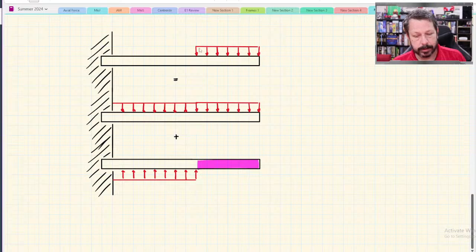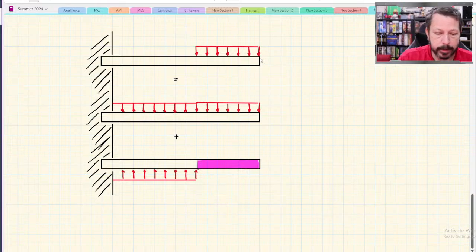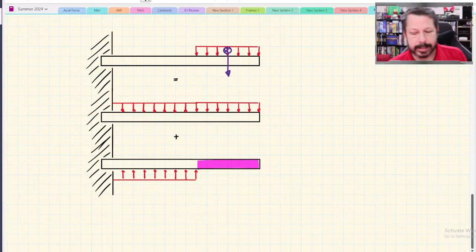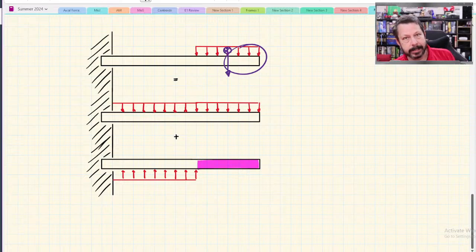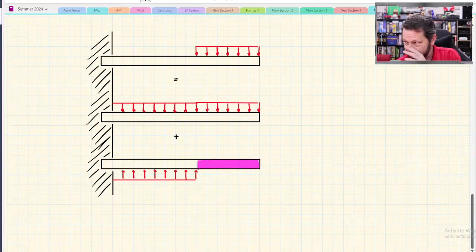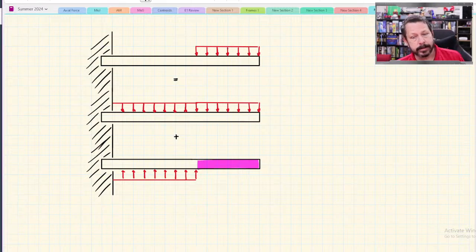the distributed load off to one edge at the end of the beam, whereas doing the lumped version here does not give me the exact same effect for that section out at the very end of the beam. So that one probably doesn't show up as much, but I wanted to show you that it's not always that you have to add them together. Sometimes you can subtract them, or in this case add a negative version to counteract one. That might be a way to approach it.